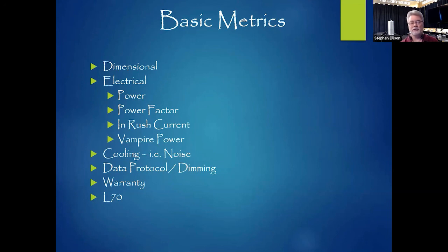So LEDs aren't like tungsten halogen lamps. Tungsten halogen lamps die. The filament breaks, you go from light to no light automatically, and you're never going to get it to come back. Sometimes you bump it and it'll flicker, but that's only the filaments brushing up against each other. It's not going to last. LEDs don't do that. They fade away. At their L70, 70%, they're still outputting light, and they might do that for another 5 years. They're still going strong, kind of, but the rating means your output is going to be dropping.